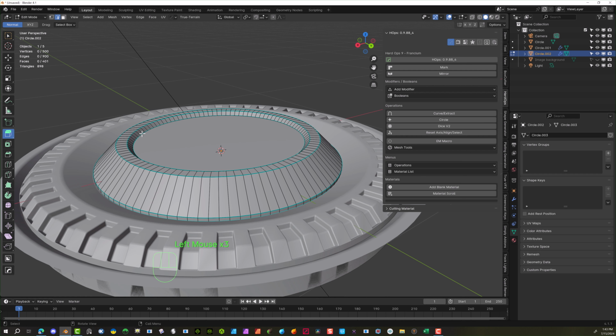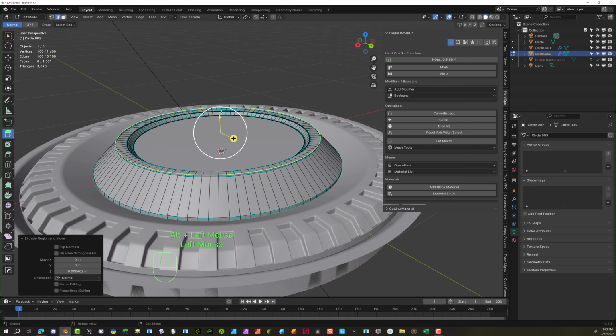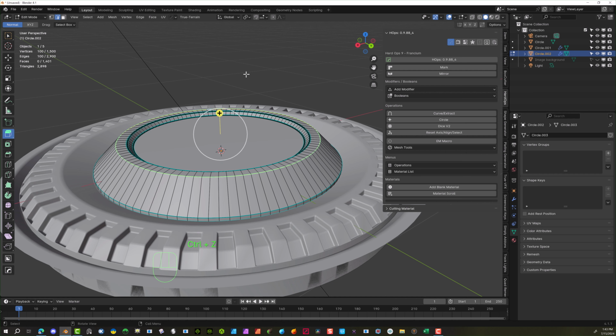Cool, now we're going to hit this other line here, and this line here, and we'll hit Control B, as in boy, to pull this out to get a nice bevel. And now let's select this with the Alt key. Again, same thing. Pull that out.